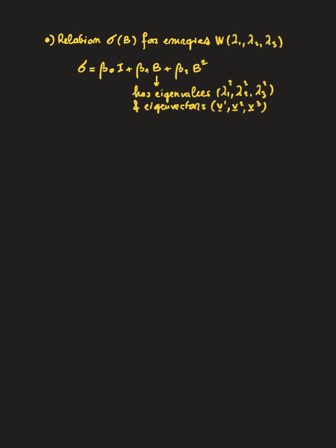So you see what happens here. Imagine we write it out by hand. This is just a diagonal tensor, so 1, 1, 1. B will have lambda 1 squared, lambda 2 squared, lambda 3 squared, and everything else 0. And also this guy will be exactly like this. It will have the same eigenvectors, but instead there will be lambda 1 to the fourth, lambda 2 to the fourth, lambda 3 to the fourth, and all the rest 0. What does this mean? This means actually that the reference in which B has principal directions v1, v2, v3, means that v1, v2, v3 are also eigenvectors of sigma. Because you see, this is an identity, this is diagonal, this is diagonal.